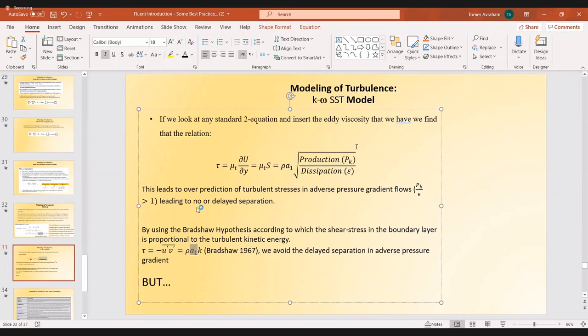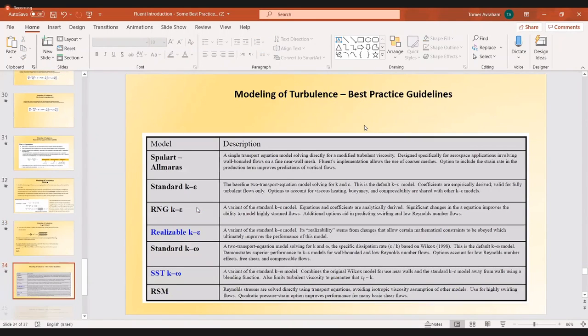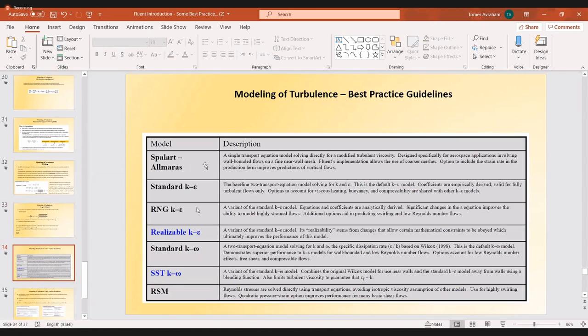So that's the difference between the 3 models we have. Turbulence models, we have Spalart-Allmaras. The Spalart-Allmaras model was tailored for aerodynamic flows, external aerodynamic flows. It's really tailored. Each term was tailored to perform very well. It's very efficient in flows around wings and stuff like that.